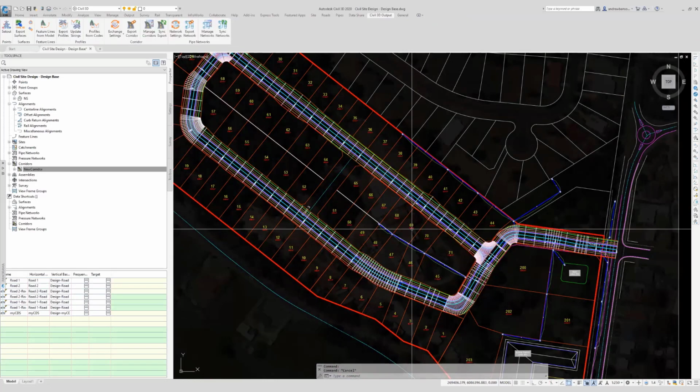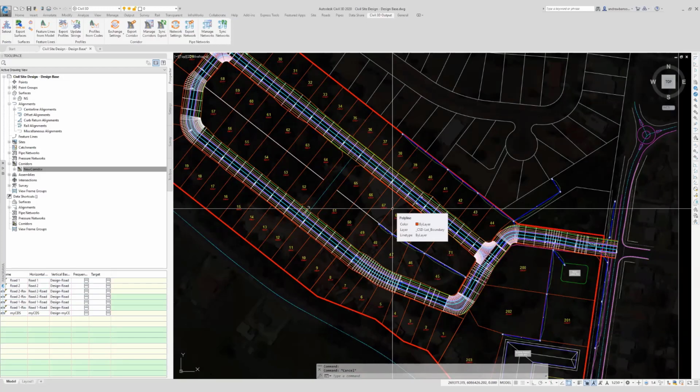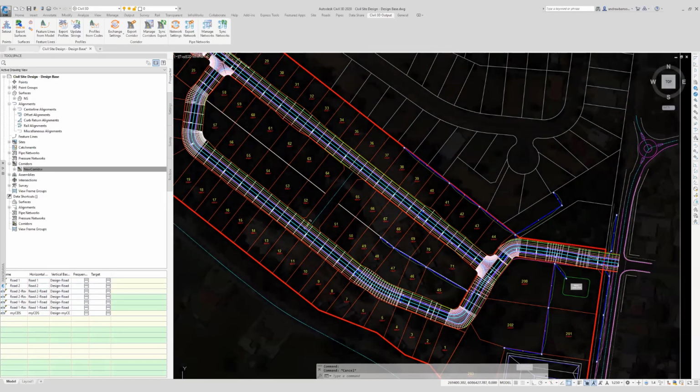Andrew, again, another interesting question connected to Civil Site Design. With the sync export, can you include it in the threads so they'll automatically run the process and update the sync? We are definitely going to be doing that. So in threads, an action will be corridor export and also pipes. So you could build a thread that whenever you ran it, also updated your corridor, also updated your pipes. Although it's not really necessary, the pipes. And I'll get to that a little bit later.